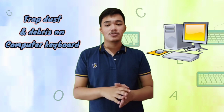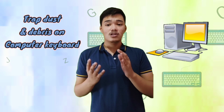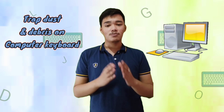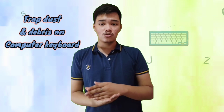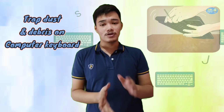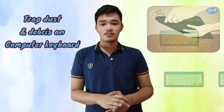So the next issue is trap dust and debris on computer keyboard. Also, it is the same as how you clean or remove dust and debris from your laptop keyboard. As I've mentioned earlier, make sure that your computer keyboard is already unplugged from the computer. Then the next thing you need to do is to turn your computer keyboard upside down, then carefully tap the keyboard so the dust and debris will fall off.